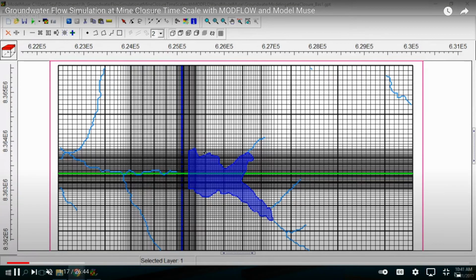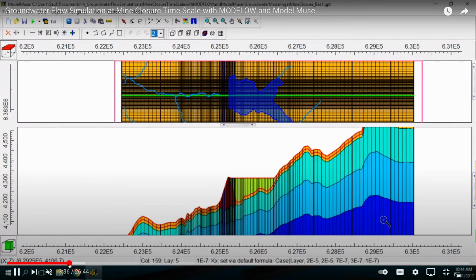If we look at each individual cell, but write a system of equations that links it to all the neighboring cells, we'd end up with a system where, if we have 100 elements in this direction and 100 elements in this direction, so 10 to the 4 elements, then we'd have 10,000 equations which we need to solve that relate the flows into and out of adjacent cells to each other. That's all it is. And so relatively sophisticated numerical models are put together that allow you to solve this system,